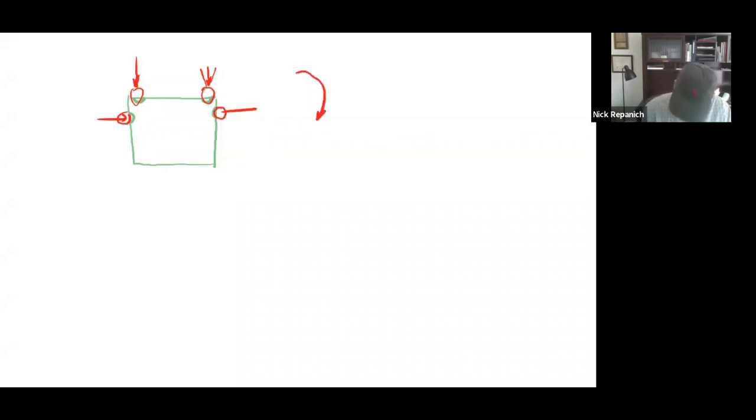Back to that very first conversation we had, this would be the side load to the bearing. This would be the, I don't know, top load. There's not an absolute name for it, but the key is that you can also have, like, this would be a roll moment around this, because these handle multiple directions. So you put in multiple grooves, and I won't take this one apart, but this one has 1, 2, 3, 4 channels of little balls inside of it.